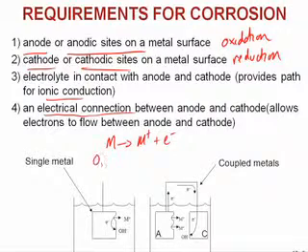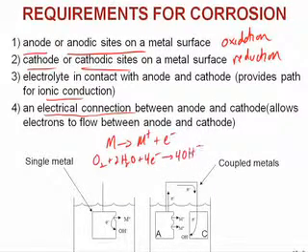In an aerated environment, like this one here, this is an aerated electrolyte, this is my water. Contains anions and cations, right? It has some minerals in it. It also contains oxygen. It's exposed to the air, contains dissolved oxygen. That oxygen can react with water and electrons to create OH-.